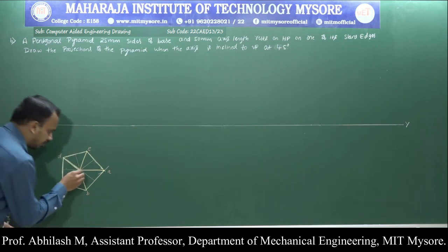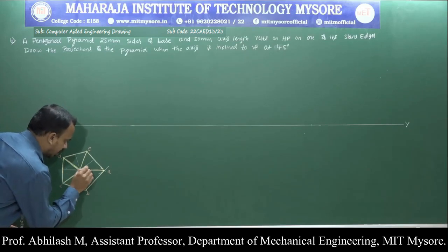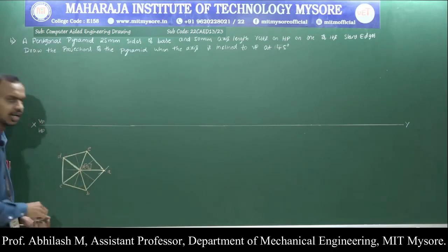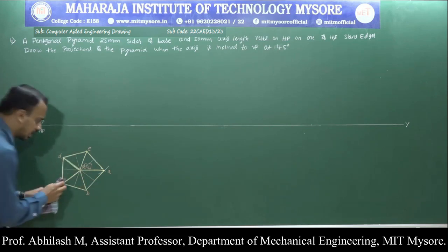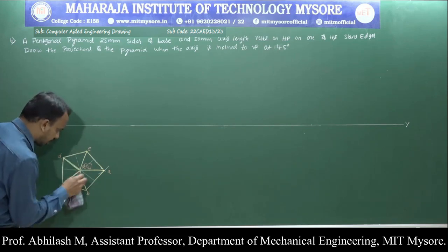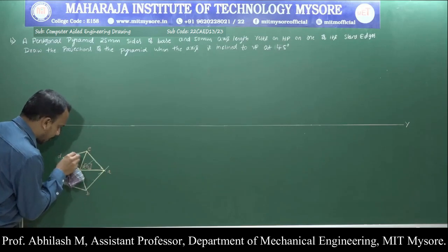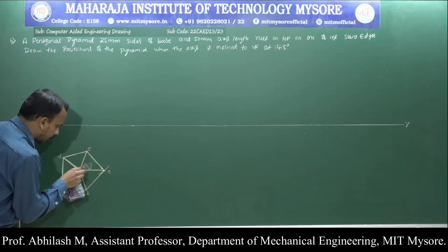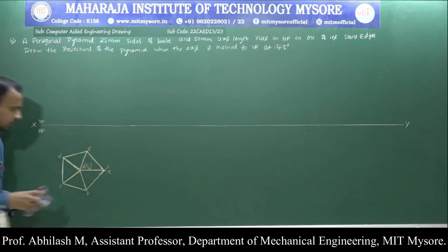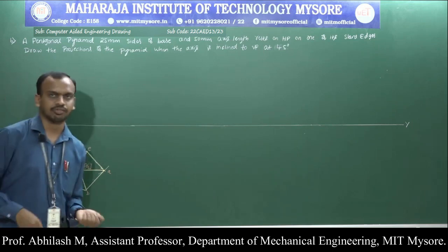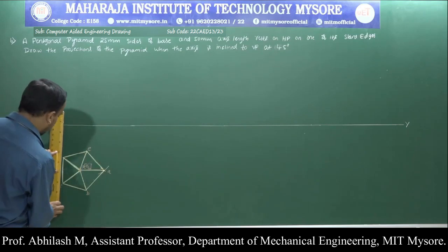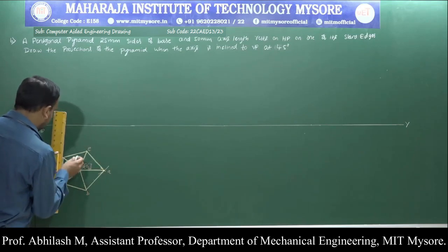So we have forgotten to name here. So this particular point will become for us O1. Either you can retain these thin lines or you can wipe them off so that it is clearly visible for us. Now let us begin with the further step, which is to draw the projection lines. Draw the projection lines up to xy first, up to xy.